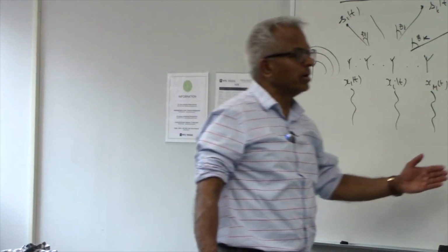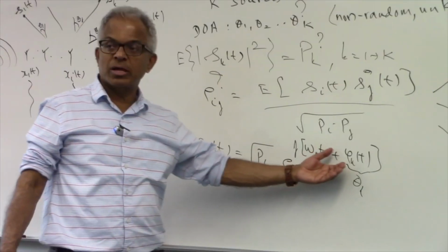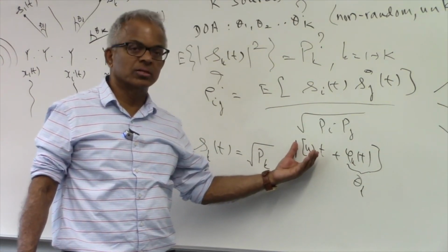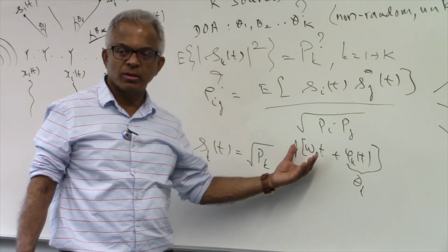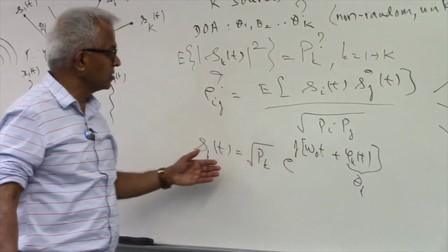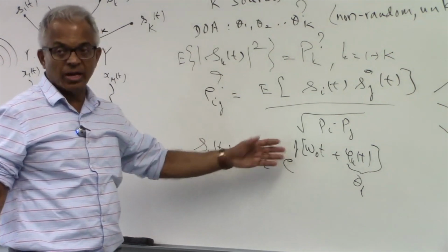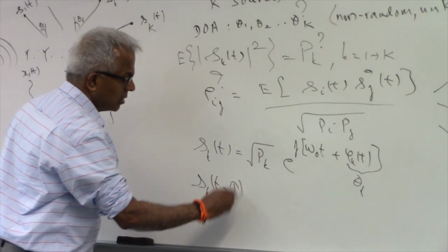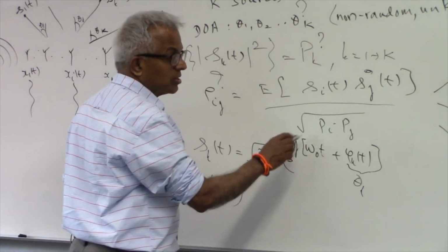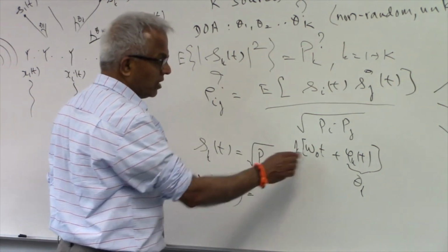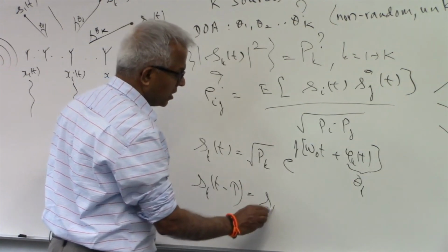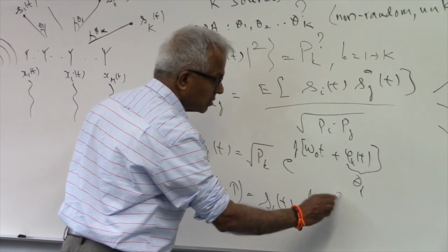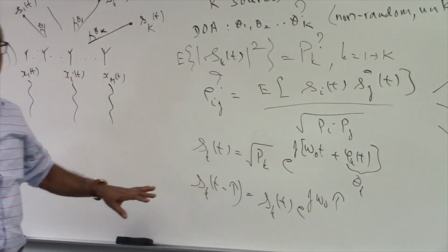If it is wideband, then of course this narrowband assumption is not possible, and here you will have to consider a significant bandwidth. As I explained to you last time, if you have a delay here, since this is the rapidly varying quantity, the fast time, this delay essentially comes out as a phase difference, right? So this is the key for narrowband.